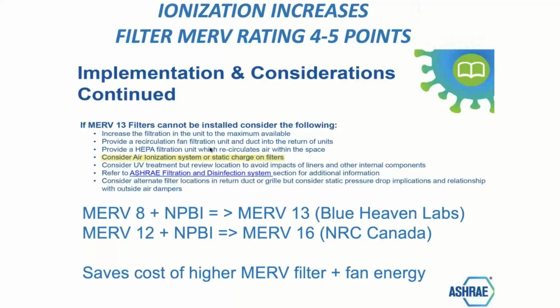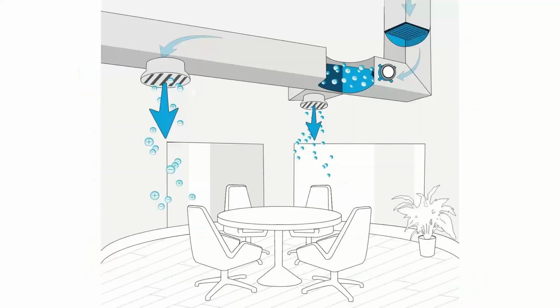On a small system like at your house, put an ionizer in your furnace, and the air from your furnace fan will be delivered to your rooms in under a minute. You're kind of good. On a big system with long ductwork, putting the ionizing device in the air handler, mixed results there. It does a good job of killing stuff on my coil because the coil is right there, but it doesn't do as great of a job in this space because they get used up.